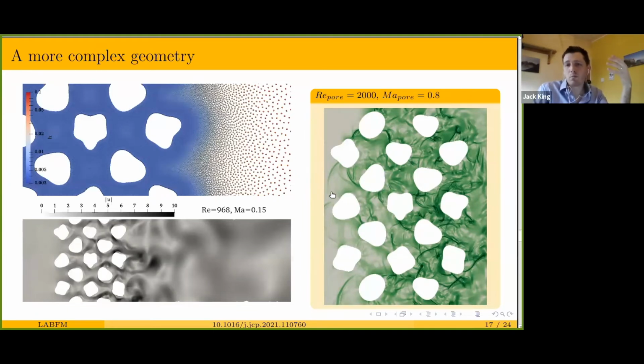And even if we use some immersed boundary methods in a finite difference scheme, they wouldn't be able to get such accurate boundary conditions. And the focusing of resolution where we want it again becomes challenging in immersed boundary methods with finite differences, because we're limited to grid stretching in a Cartesian framework.